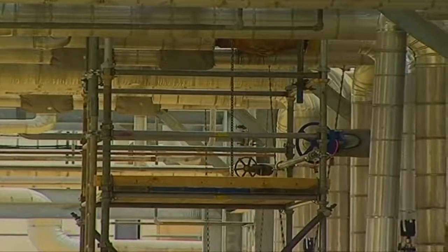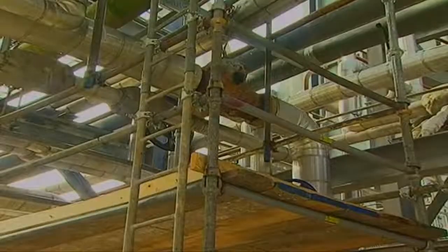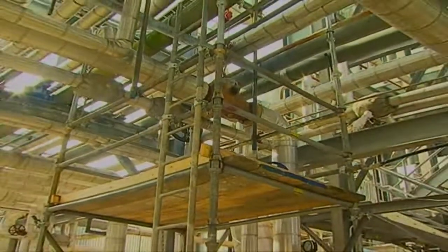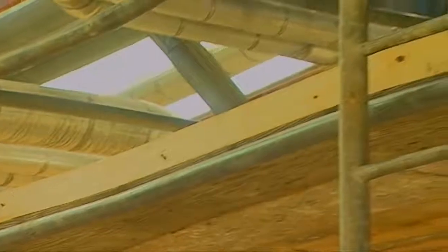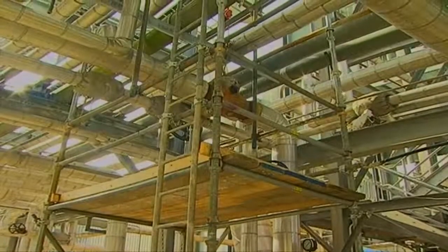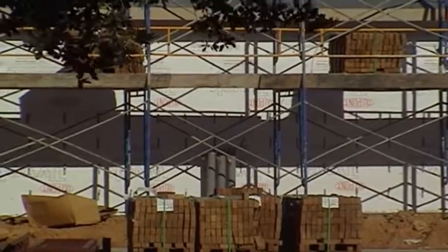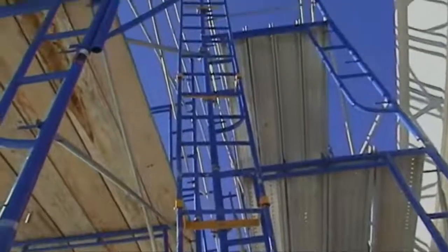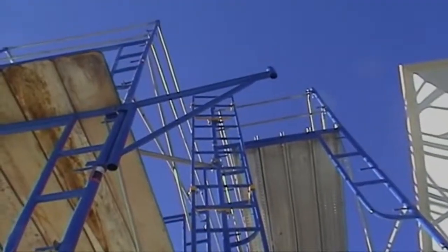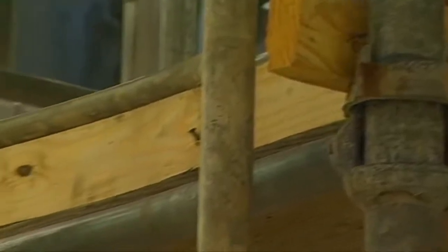The platform is the work area of the scaffold, except when it is only used as a walkway. Inspections of the scaffold platform must include safety checks of both the platform structure and how the platform is used by the workers. Each platform must be fully planked or decked between the front uprights and the guardrail supports. Scaffold planking must be able to support, without failure, its own weight and at least 4 times the intended load. Planks can be properly sized and sawn wood. Prefabricated planks or fabricated platforms may be used as scaffold planks and platforms as long as they are manufacturer approved or have been accepted by a lumber grading association or inspection agency.